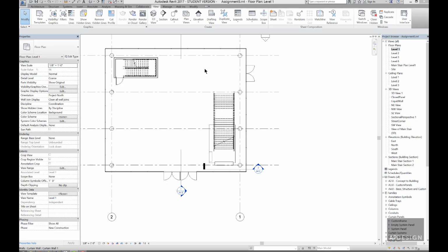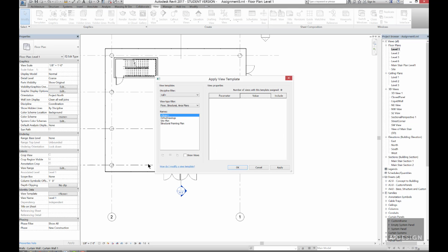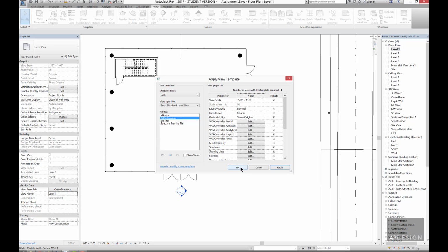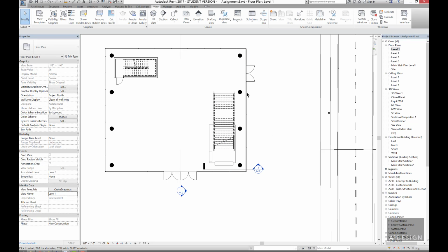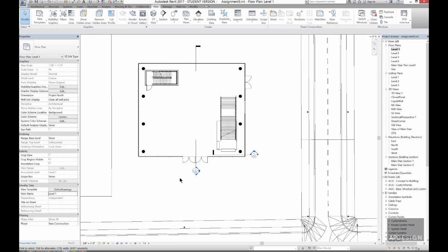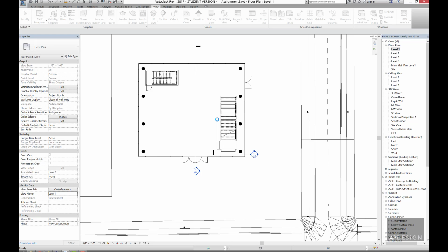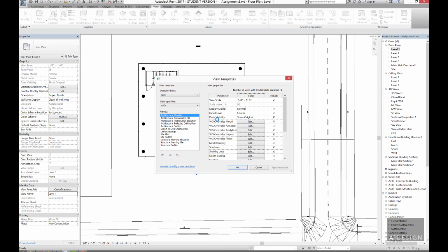Alright, in this video we're going to go into surface patterns. Before we do that, let's go ahead and apply some of our ortho drawings template. So you can see a couple of things have happened immediately as the poche was applied. The grid, the structural grid went away. So make sure that you've set this up just right. Again, you have complete control over those.